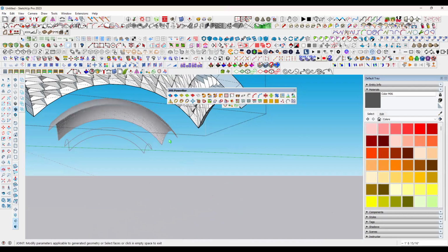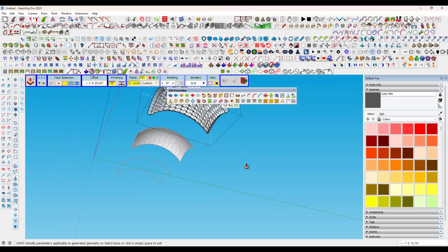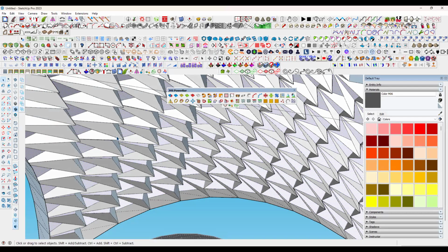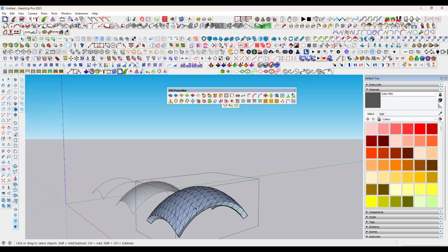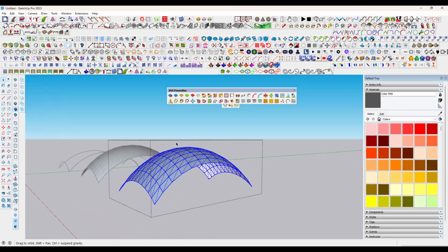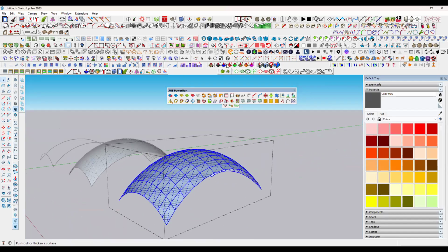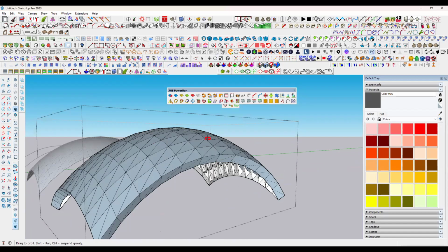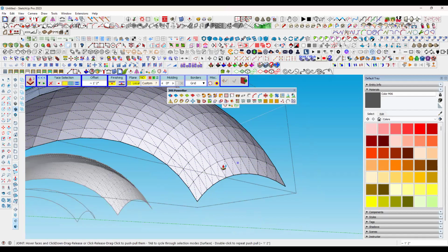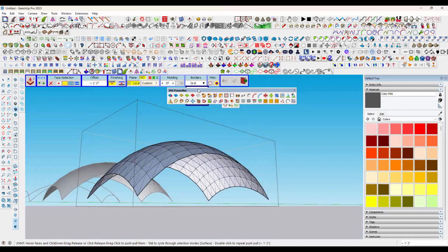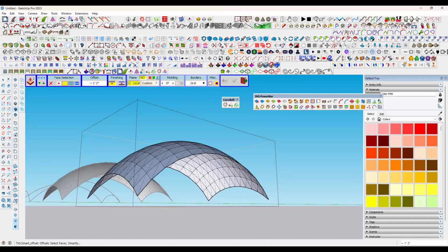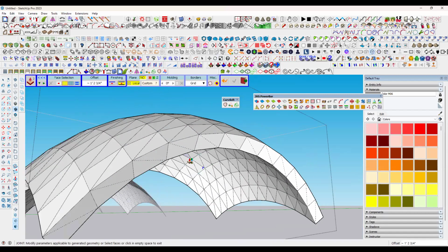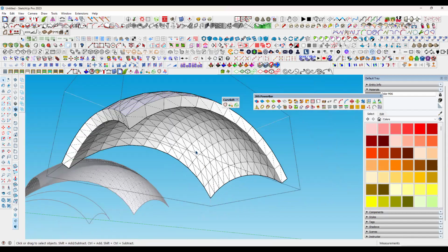Now see we got the multiple surfaces. But see even on the bottom, if you observe here, you are getting the internal faces also in this situation. So now what will I do? I'm taking one more surface here. In this situation, I'm taking one more joint push pull, maybe like this. And click OK. Now see the surface how you are getting on the bottom. Sometimes I don't want it like that. I want to click on a grid now. And on a grid, I am clicking this one and going maybe here. And click that. See the face, how you are getting a proper face.